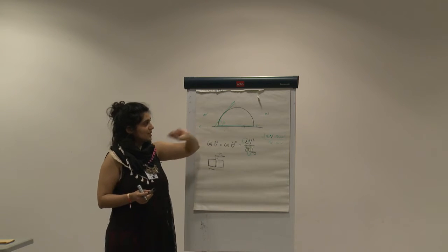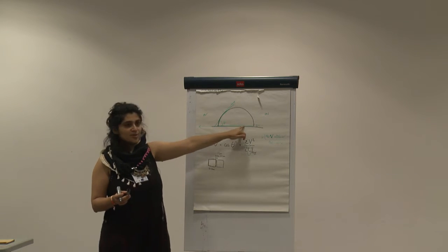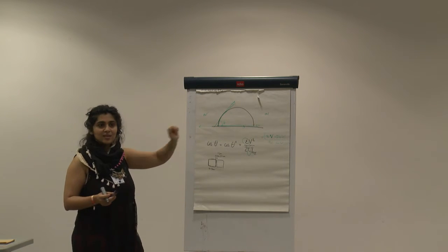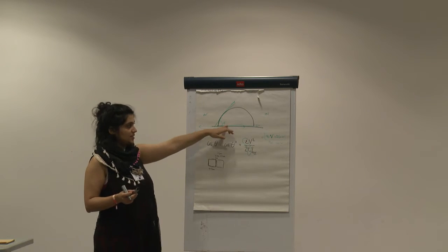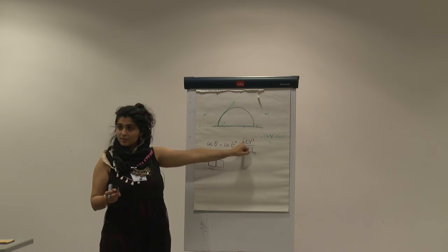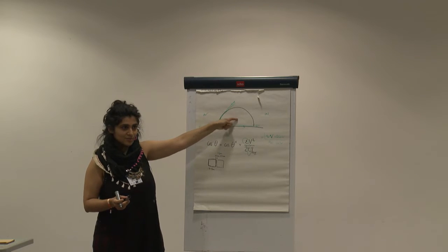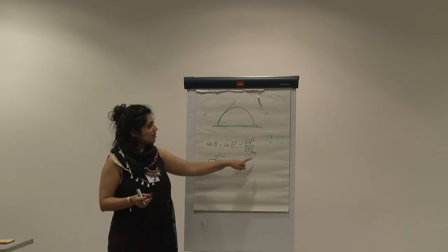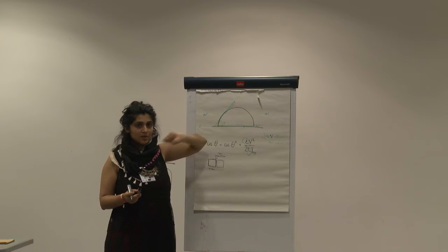So there are two ways to work with this equation. One is trying to get as thin a coating as possible. And when I say thin, it's maximum 10 microns, so even thinner than 10 microns. Then we're trying to get a coating with a higher dielectric constant, but insulating, because I don't want sparks in between these two. And then we can also try to work with the interface between the two of them.